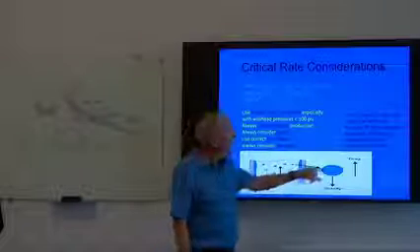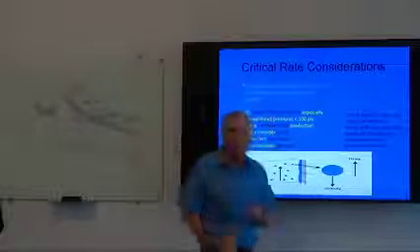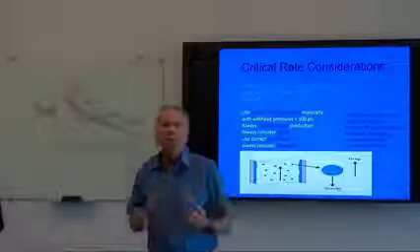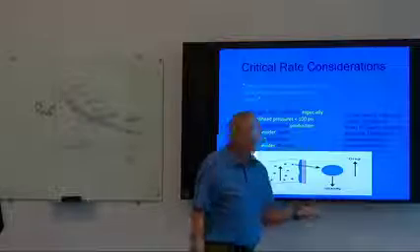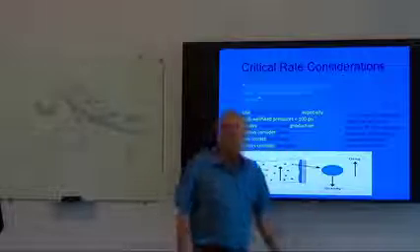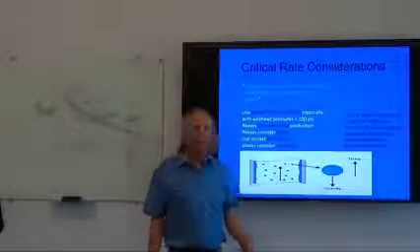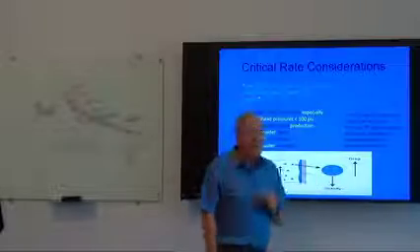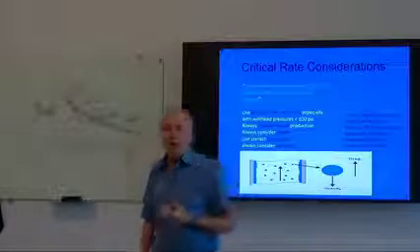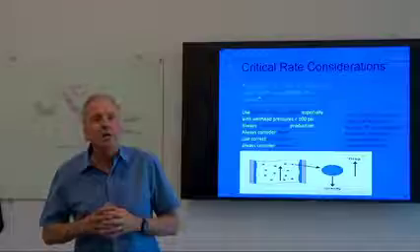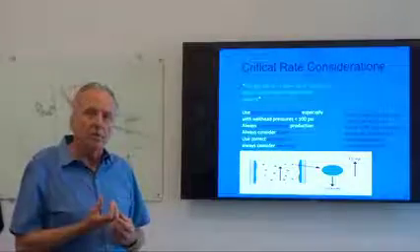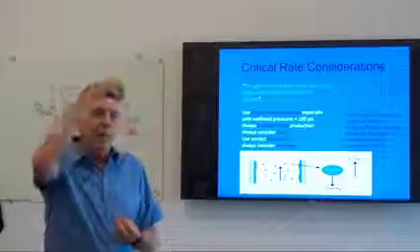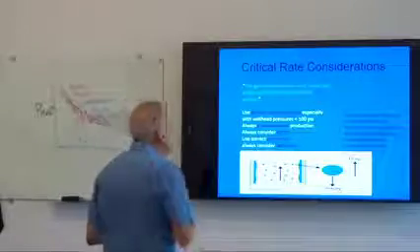But let's just take a droplet aside for a moment and look at the forces acting on it in this environment. One of which is gravity, of course, which is ever present. Gravity is going to try to pull that droplet back down into the ground. And we're going to try to counter that with a drag force. The drag force is just a function of this wind, the gas, blowing past the drop and trying to draw it towards the surface.